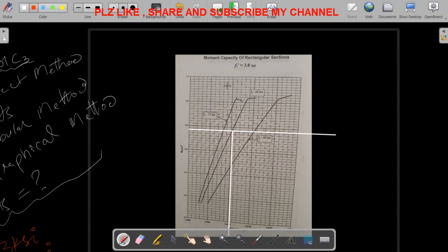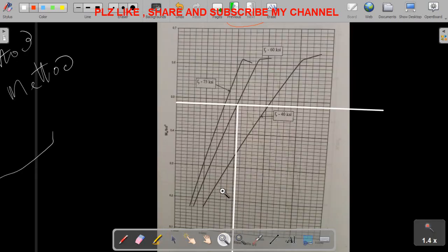I have already discussed these graphs. In these graphs you will see this graph is drawn for 3 ksi concrete. These graphs are available in the McCormac book and the MacGregor book, in the last pages. These graphs are also available online. So let me discuss this graph. My Mu divided by bd² value is 0.444, so roundabout this value is 0.444 ksi. This is in ksi units.